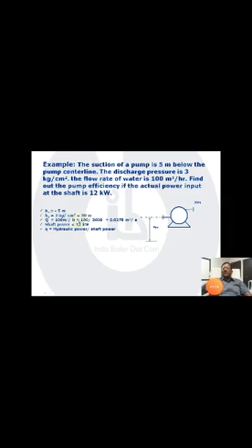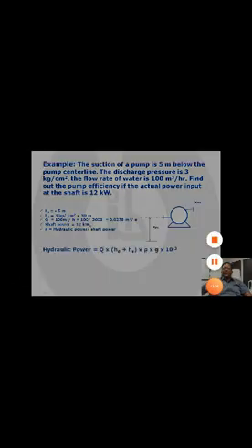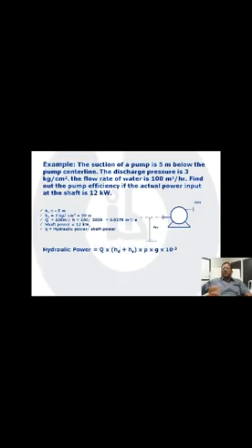Again, the shaft power is given. Mechanical efficiency is hydraulic power by shaft power. If I use the equation, put the values of HD, HS and Q, I get the hydraulic power as 9.54 kilowatt. Therefore, the mechanical efficiency is hydraulic power by shaft power, which comes to 79.5%.